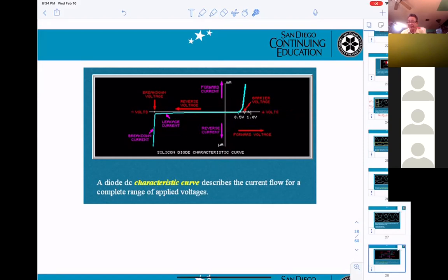The voltage goes up to 0.5, 0.6 or 0.7 volt and can no longer increase. It stops there. However, the current keeps going, which means the diode allows current to flow through. But the voltage VD of the diode will be either 0.5, 0.6 or 0.7 volt.